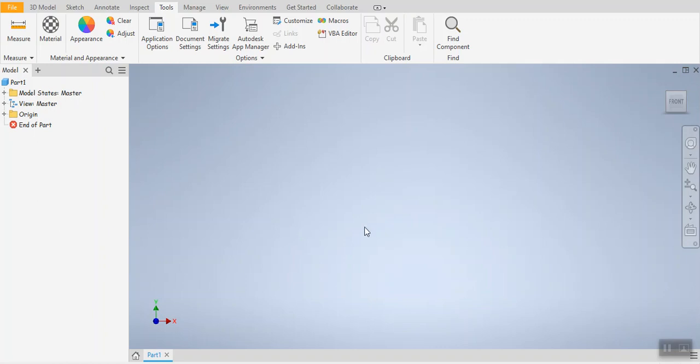All right. So when you start a part drawing, first thing you do is you select a plane, XY, YZ, or ZX plane, and you go to Origin, click on the plus button next to the Origin. It opens the folder for you. I'm going to create a sphere first, so I'm going to select the YZ plane.